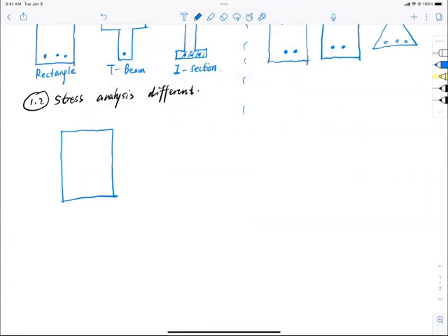So that means that I have my effective compressive zone, and let's just call it the actual compressive zone, right? Let's call it actual compressive. So from the strain diagram, you know that this is lining up with the neutral axis, and this so-called C is the actual compressive zone, right?